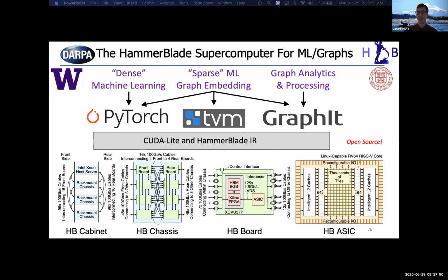Not currently. So currently each tile runs its own thread of RV32I-like vanilla core processing. And the idea here is that these components like PyTorch and TVM are able to map into the backend as a single GPU thread like that. So this mapping works really well. But if you start splitting up SIMD within that, the tools don't really know what to do with that because you're almost parallelizing too much. And our answer is just add more cores. That's a fine answer. We'll see how that works.